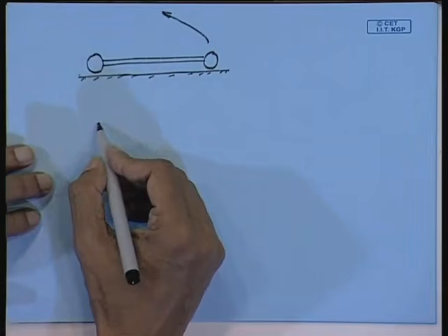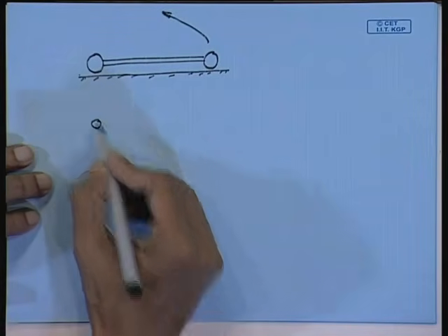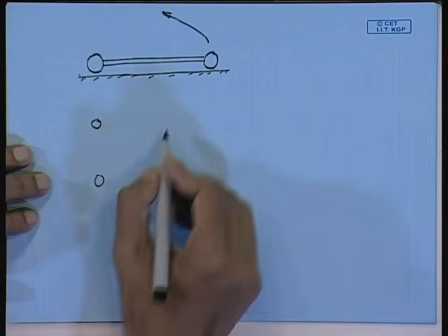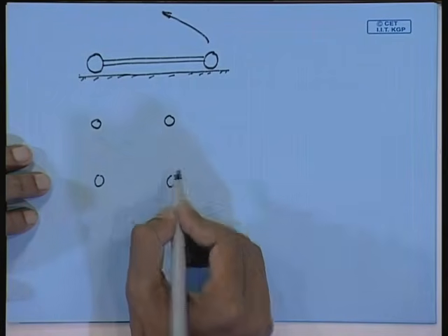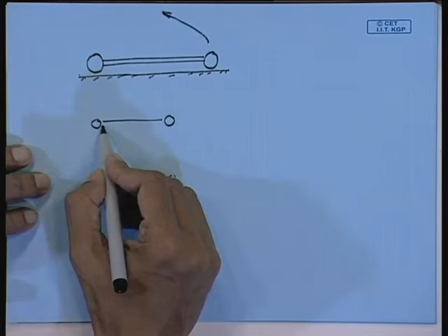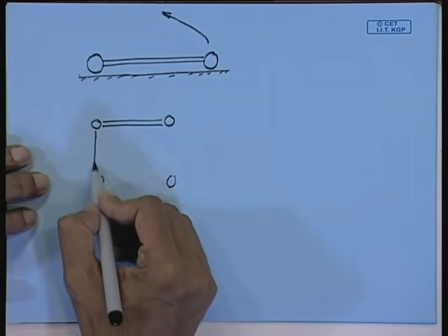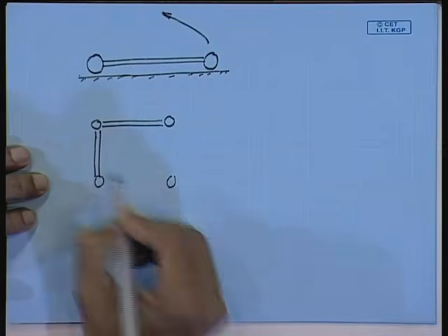You lift this up, so it gets in the vertical mode, you bring another panel by means of cranes and join the bracing members, weld the bracing members together. So, that is how your jackets are built.